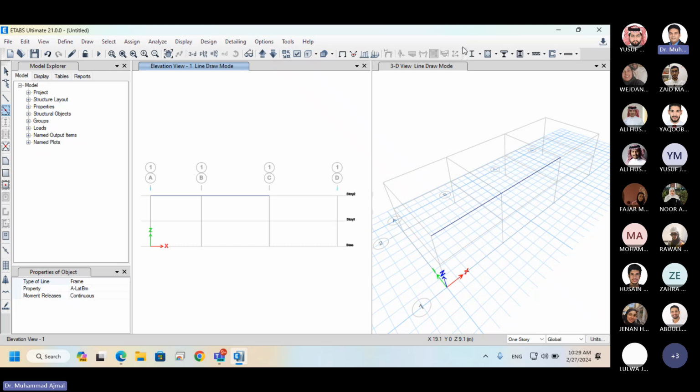If your grid line spacing is not correct, it is taking the same space where you are putting your cursor. So that's why I already defined 6, 8, 8. Now you can define any line and then take node to node points and connect your beams there. That option can work, but the best approach is that your grid lines must be defined before you start modeling.